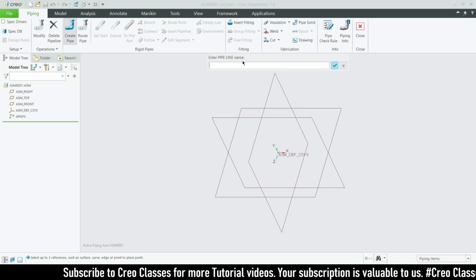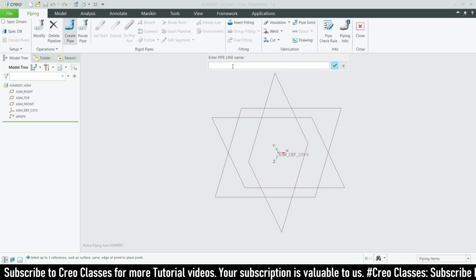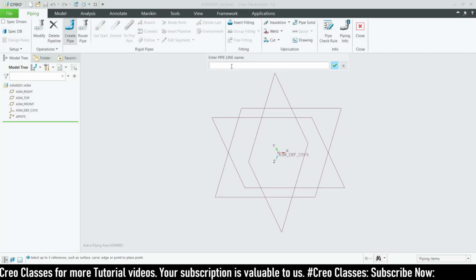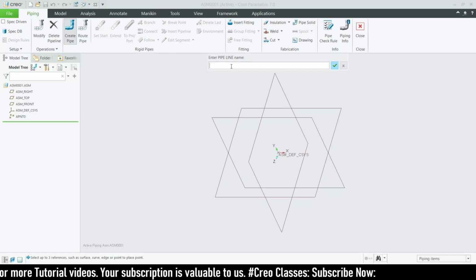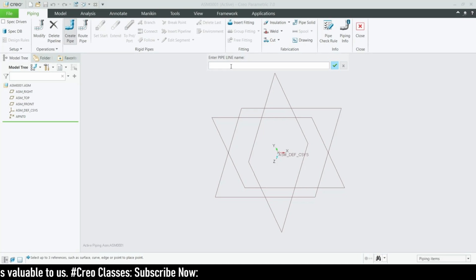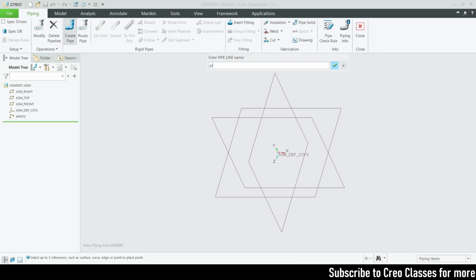When you go for create pipe, you can see we have to enter the pipeline name, which we saw in our previous piping tutorial itself. Let me explain this again. If you need to know the details about this entire piping tool, you can watch the tutorial which is available on our channel. We can directly enter the pipeline name. You can give any name for your pipeline, this is just for our reference. I'm just going to give this pipeline name as piping 1.